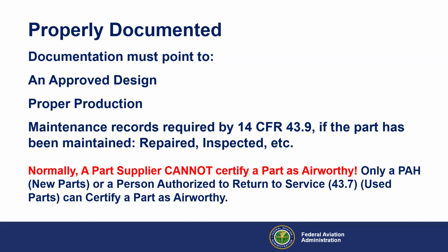So normally a part supplier or distributor cannot certify a part as airworthy. Only the production approval holder or a person authorized to return to service under 43.7 that we've already looked at for used parts can certify the part as airworthy.